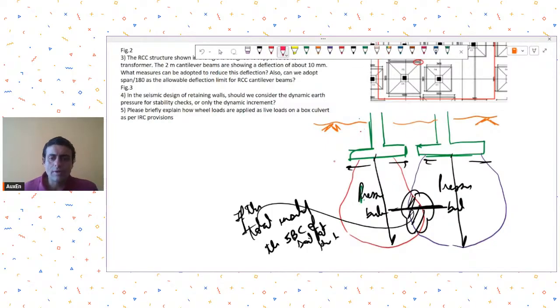Because whatever footing you have cast has been designed using the SBC at the footing base, but the pressure bulbs intersect each other at a lower depth or at a greater depth.